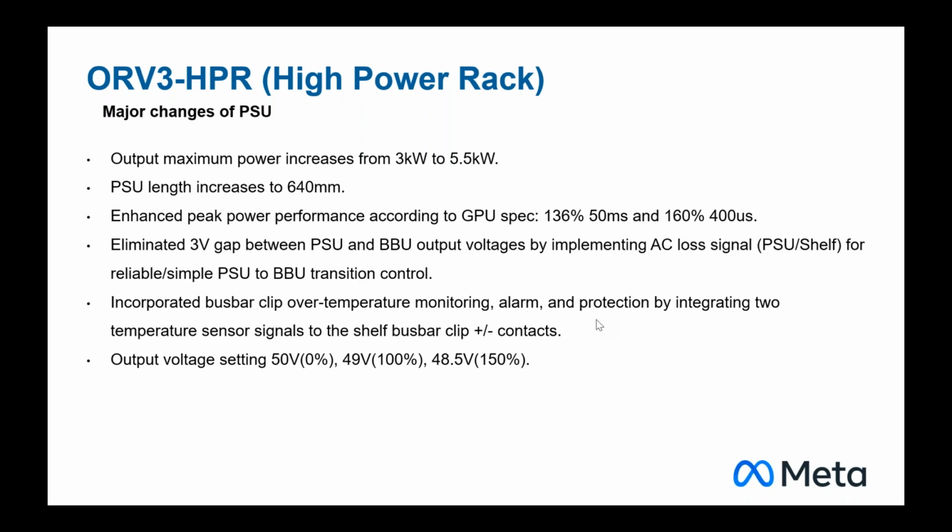To maintain the 5% tolerance, including load transient, even if I have a tight output range on the power shelf, it may not satisfy the 5% target at the load, because there's distribution loss, inductance, cabling, and the DC-DC converter itself has some voltage drop. Although it's a fixed ratio 4-to-1, there's voltage drop, IR loss, magnetic loss. So very likely they still cannot use the 4-to-1 fixed ratio if plus or minus 5% is a hard requirement.